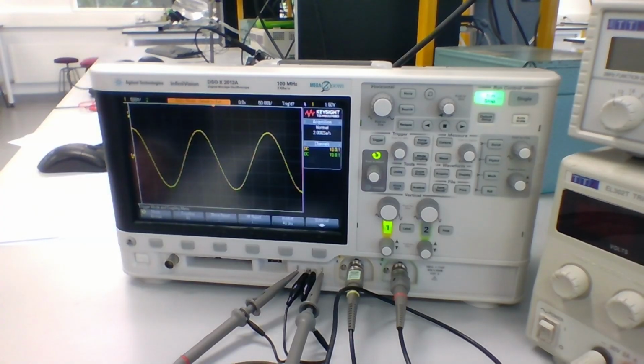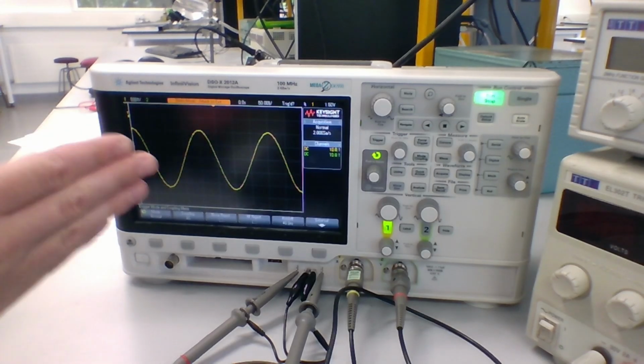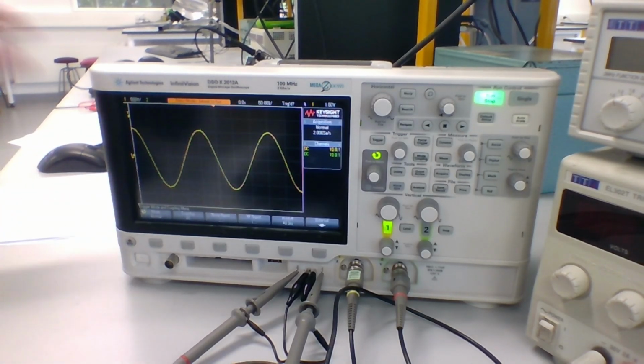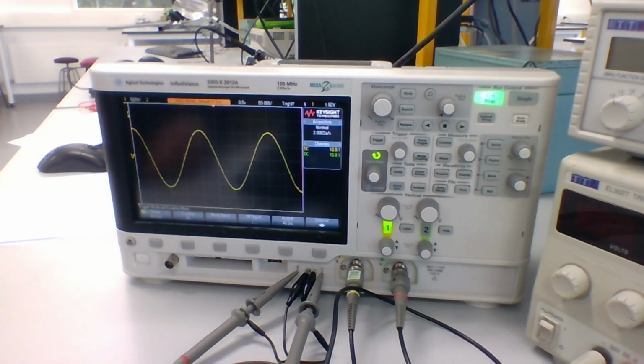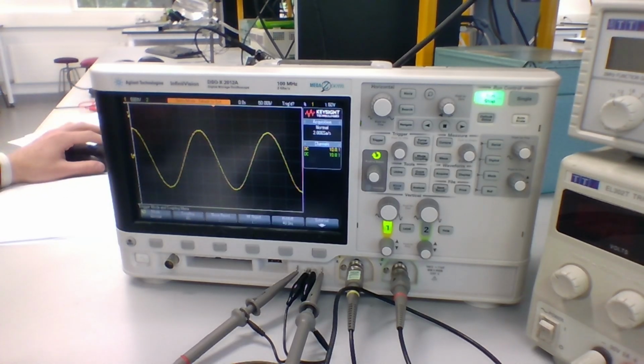This will not update, so this can be quite useful if you want to avoid having things change. Maybe you're capturing a small burst of voltages, say from a digital signal, and then you don't want that to update. The auto triggering will just wipe off the screen. Normal triggering will retain that on the screen for you so you can actually see what's going on. It's called normal triggering because this used to be the normal way the oscilloscopes were triggered, as opposed to being automatically triggered. So this is a bit of weird terminology there.